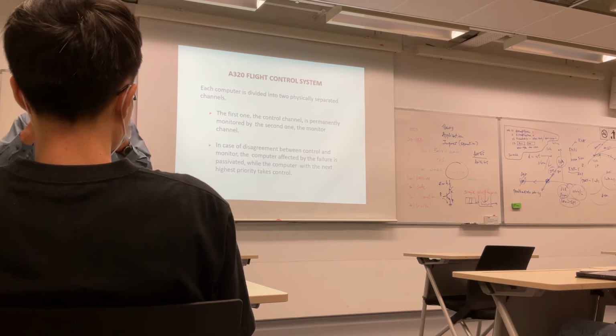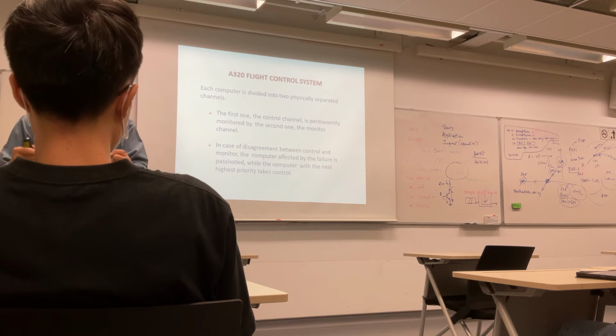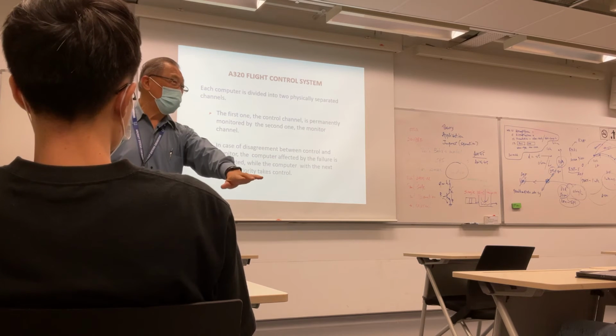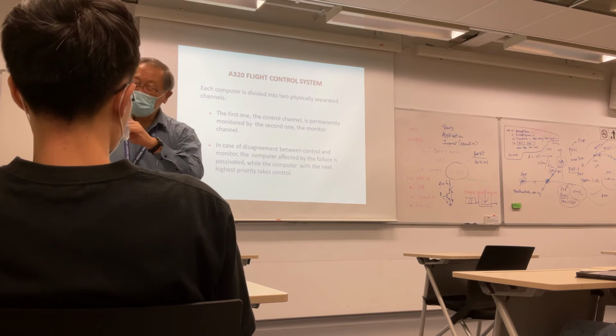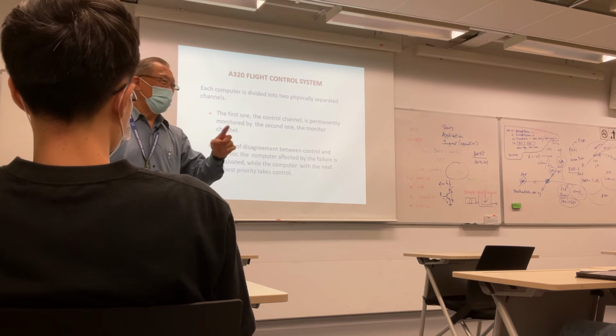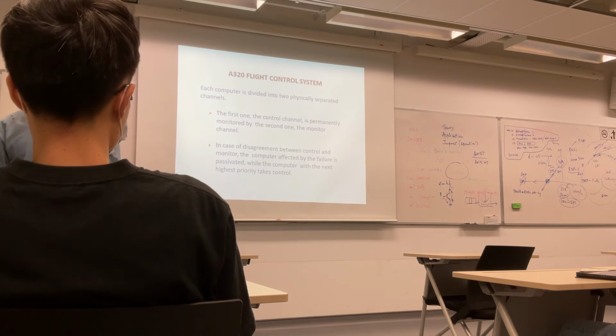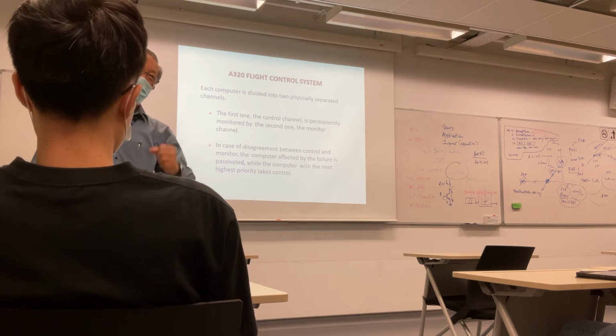So the co-pilot had a problem trying to control the aircraft, because the pilot was leaning onto the control column. So that is not fail passive. That means this guy failed and it is interfering with the co-pilot. Bad design. That's why now the aircraft don't have that, right? You only have one joystick.